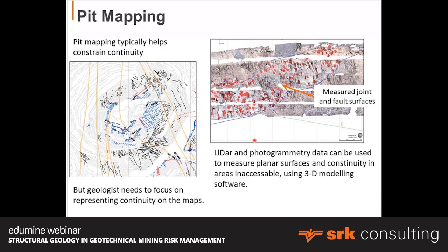And we can use LiDAR and photogrammetry data sets, sometimes from unmanned airborne vehicles, UAVs, to scan and produce three-dimensional images of our pits. And you can import these into certain software and actually digitize and measure the orientation of structures and define the patterns and the continuities.